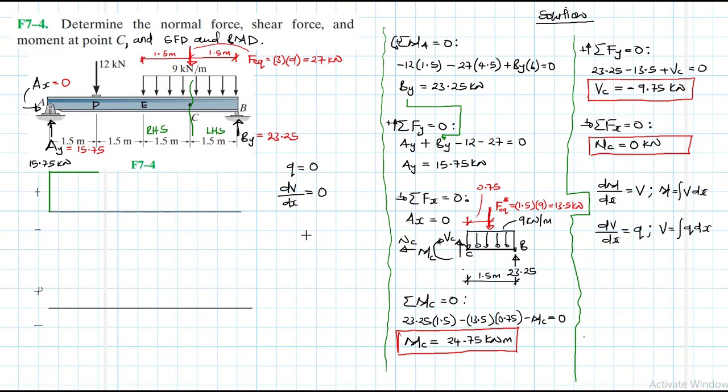So those two are going to interact. We'll have 15.75 minus 12. What does this give us? This gives us 3.75, right? So this shear will be reduced to this point here. Let's imagine that is our 3. So this point here is our 3.